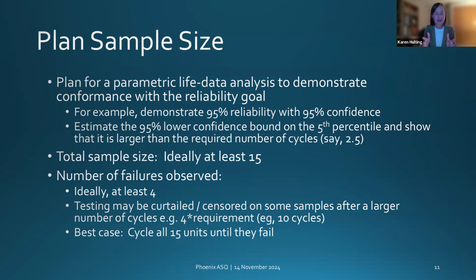The advice that I most often give out right now, and this of course depends more than a little bit on the specifics of your product, so the numbers I'm saying here might not apply completely broadly, is that it's not a bad idea to try to talk a project team into starting at least 15 units on test. Why 15? It's a minimal number to have an idea of what that distribution shape might be.